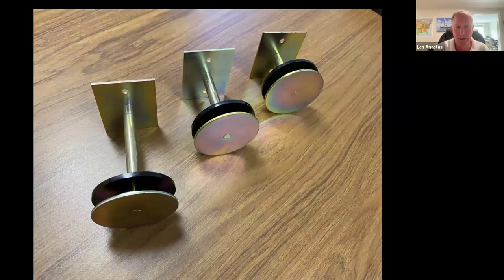So here's the bracket. We have the base plate and then our standoff, which is the round part here. And this is the thickness of your insulation. Here's your insulation retainer that's going to crank down on top of that. We have our top plate, which threads in and out. There's an inch of adjustment built into this, so you can adjust them all to the same plane and then put your attachment rail on there, which 99 times out of 100 has been hat furring.